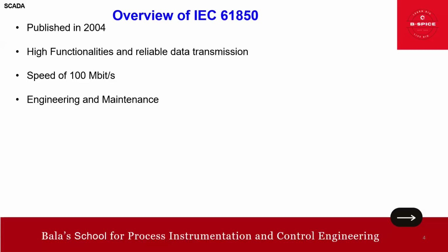And yes, it is more than just a protocol, friends. IEC 61850 also provides benefits in areas of engineering and maintenance, especially with respect to combining devices from different vendors. Then, an object-oriented and application-specific data model focused on substation automation.